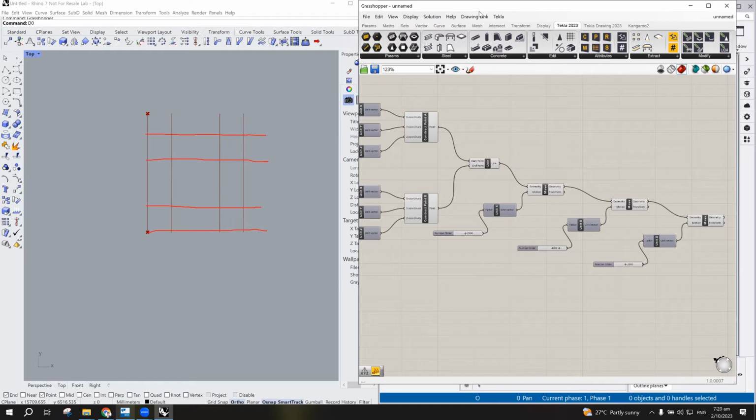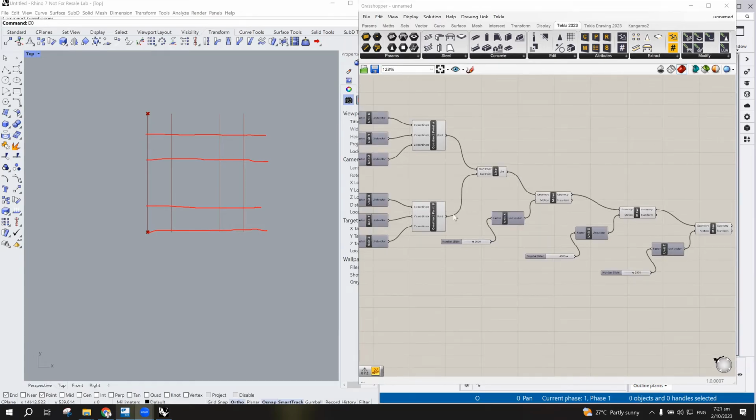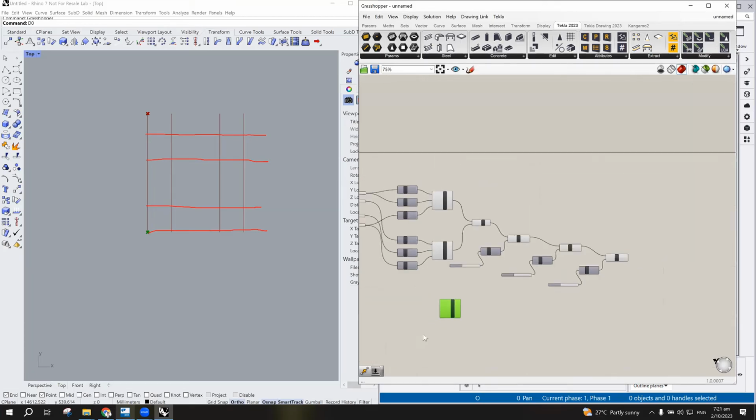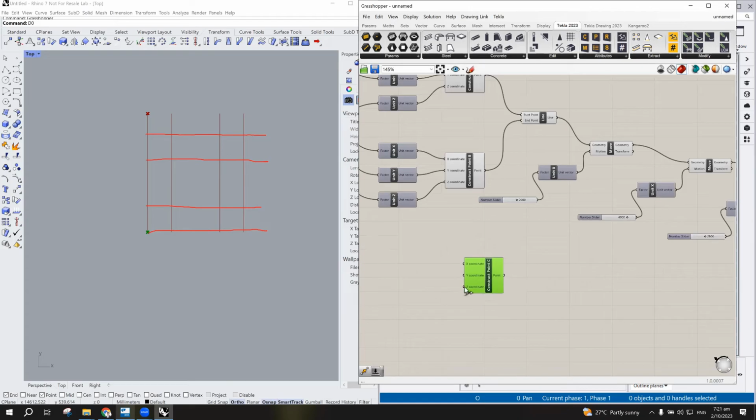You need to add a construct point on the x direction, because as you notice here, I have point A, point B, then there will be a point C. So meaning here, you can just simply put a construct point, and then this one will be point C, instead of creating a new one. Let me show it. Point C, then the movement of the point C is on the x direction.